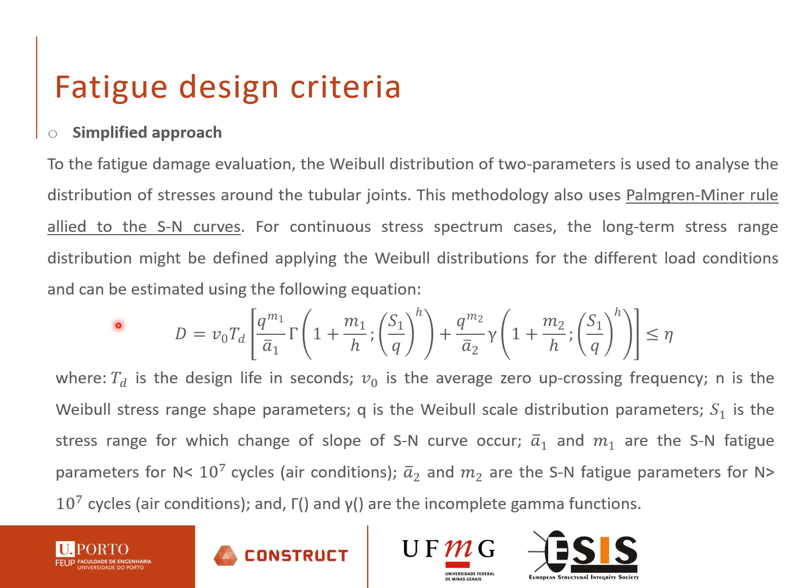Fatigue evaluation in tubular joints is essential to the design of offshore structures. For the fatigue damage evaluation, the two-parameter Weibull distribution is used to analyze the distribution of stresses around tubular joints. This methodology also uses the Palmgren-Miner rule allied to the SN curves.